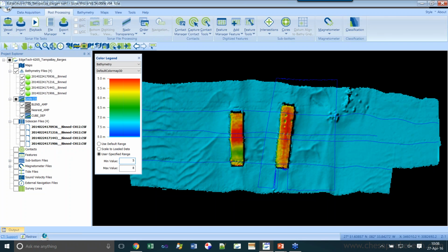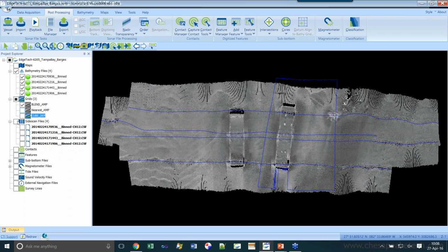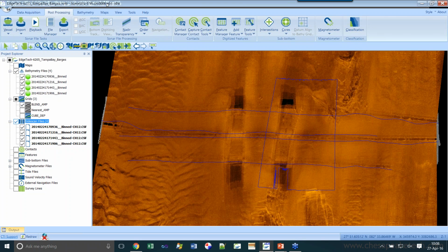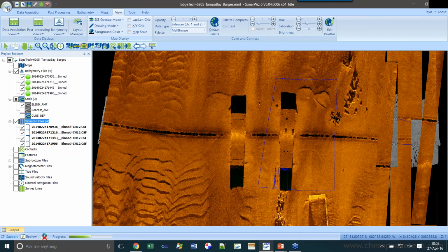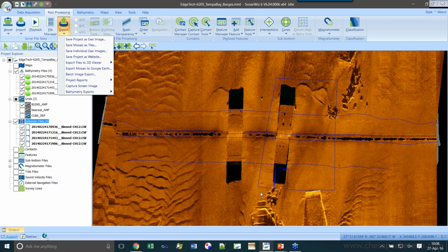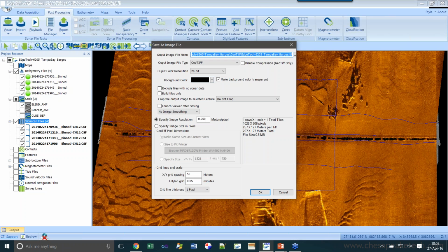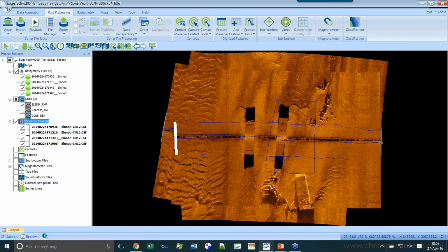Oh, let's make one more geotiff, just to compare the difference between an amplitude grid and the side scan grid. So we'll switch the side scan mode to cover up, because I think this has the best resolution. And now we'll export that as, all right, there we go.